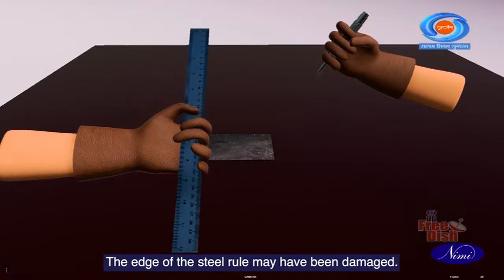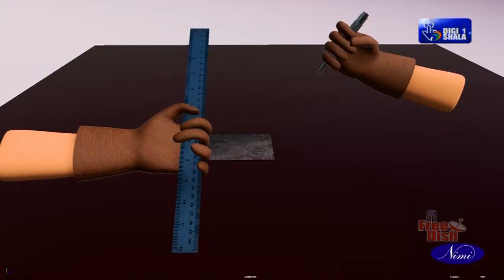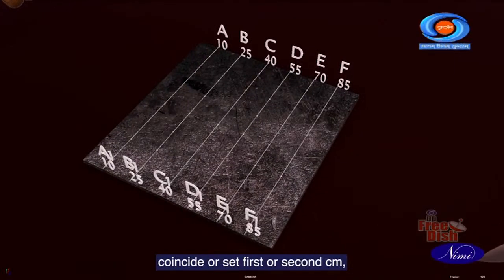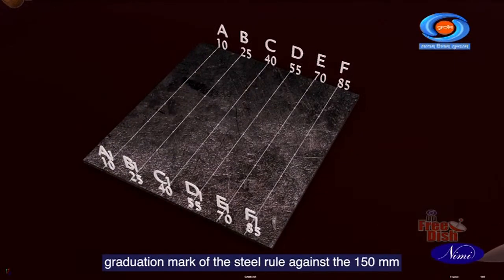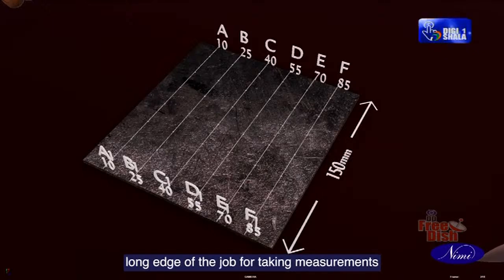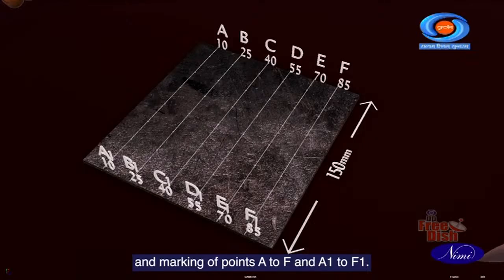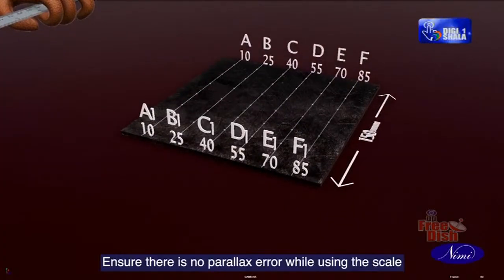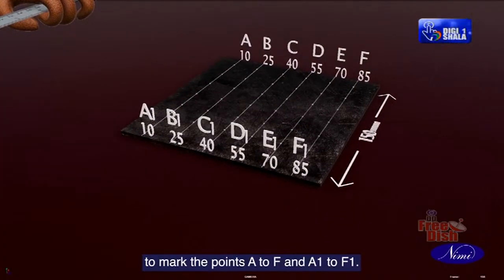The edge of the steel rule may have been damaged. To avoid wrong measurement, coincide or set the first or second cm graduation mark of the steel rule against the 150 mm long edge of the job for taking measurements and marking of points A to F and A1 to F1. Ensure there is no parallax error while using the scale to mark the points A to F and A1 to F1.